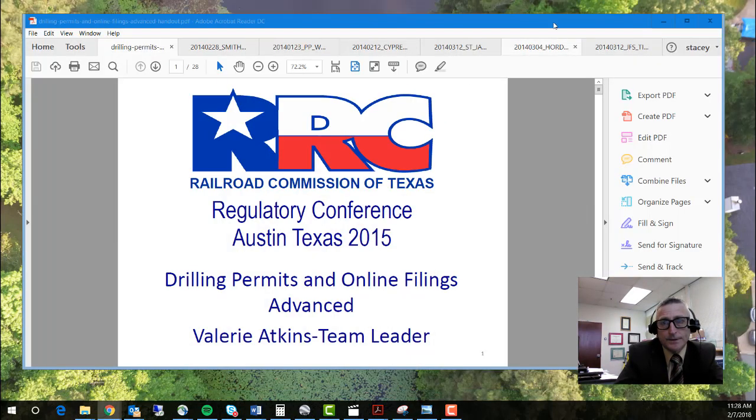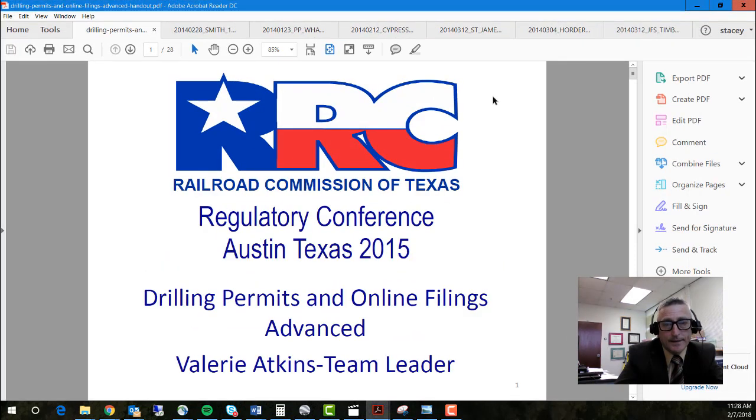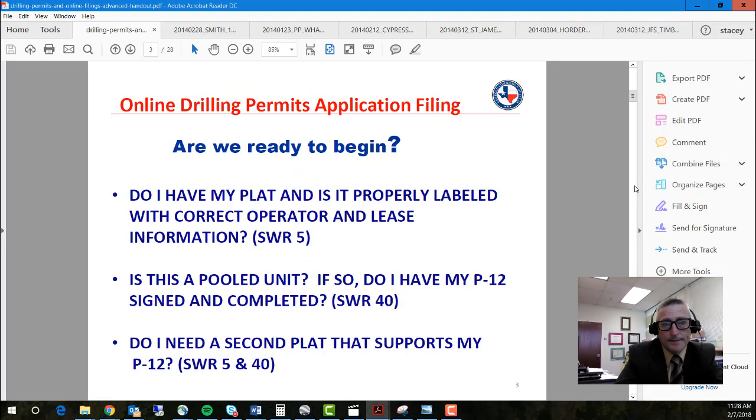Now, when you look at using a GIS to submit things specifically, you're going to be filling out a form. For the regulatory agency, for drilling permits and how to go in and fill that out, each government or state has different requirements. But for the most part, let's take a look at the Railroad Commission. They look at taking the information that's on the plat and typing it in, and it's sometimes subject to errors and problems. We can actually make a form builder that fills in the form for us from the GIS.